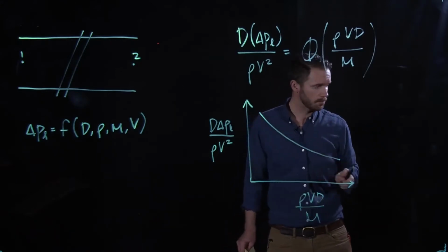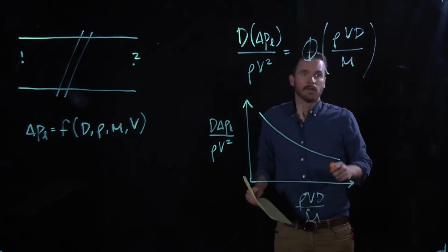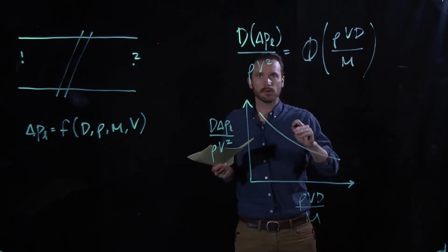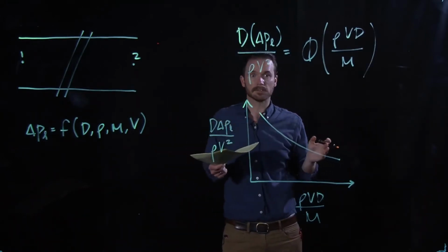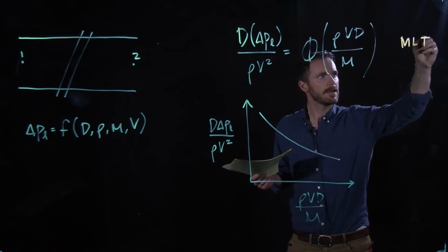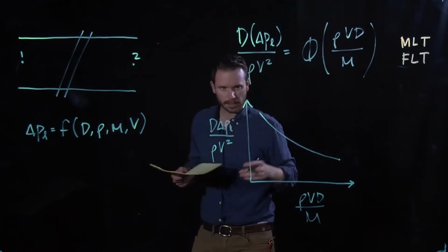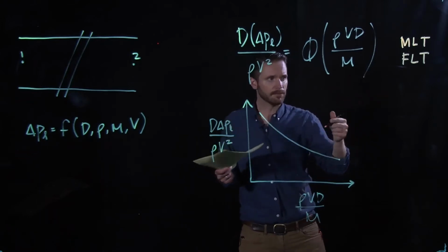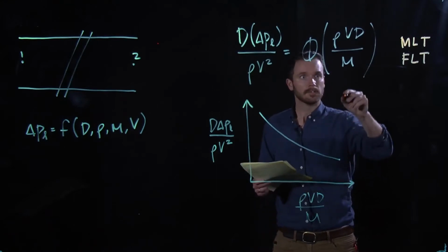One of the things that I mentioned that's really nice about this is that each of these terms is dimensionless. Now, when we talk about dimensionless parameters, typically what we do is reduce each of these individual variables down to its most fundamental basic dimensions. There are 2 different basic dimension systems that we use: mass, length, and time, or force, length, and time. And it doesn't really matter which one you use. The textbook oftentimes uses force, length, and time. But we're able to say, okay, for example, each of these. We'll do one of these examples.